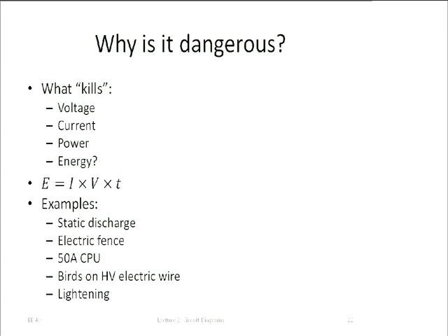Birds on an electric wire, you know, they sit on the high voltage wires. Why do they not get killed? Why don't they all fall off? Exactly. The voltage across the wire is everywhere the same, roughly, right? The drop hopefully isn't very large in the wire, and they put their feet on there, and their potential is now 300,000 volt with respect to ground, but their feet are not long enough that they can have one on the wire and the other one all the way down 20 meters or so.